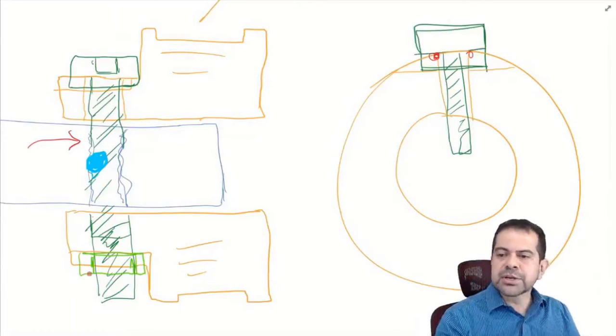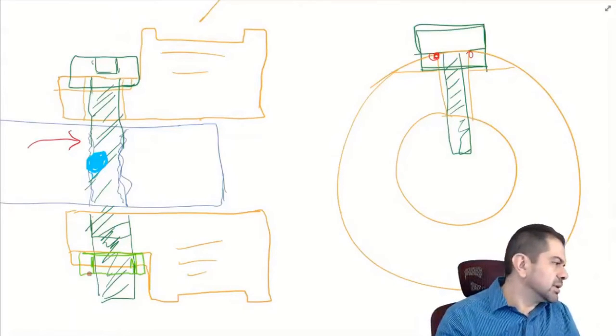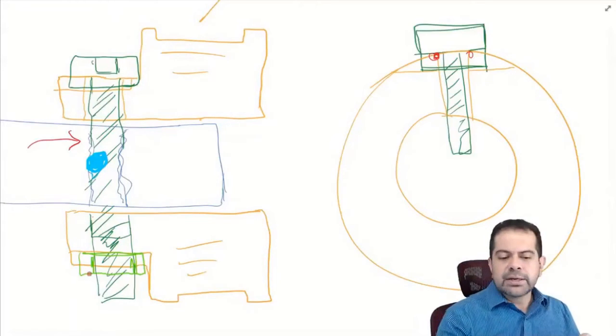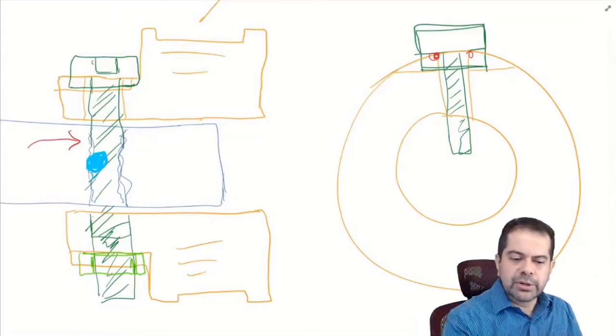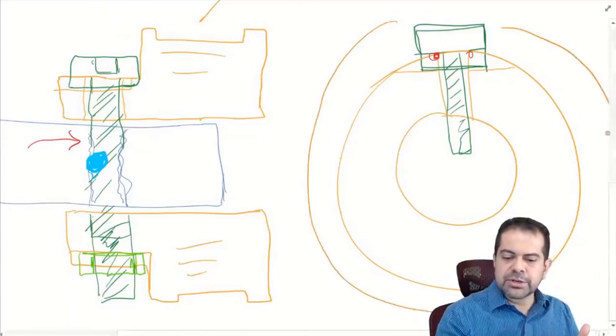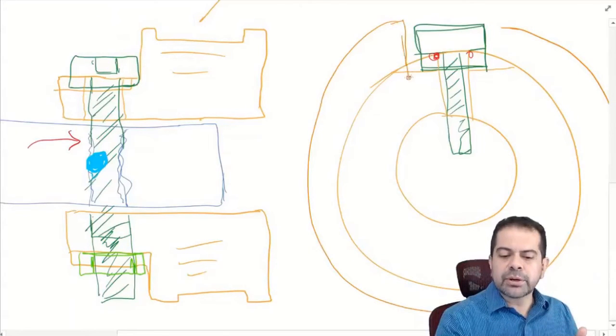Things to consider, and we're about to wrap it up. You suggested a counterbore. Yeah, if you have enough of a surface, depending on the size of the parts, you could add a counterbore. I think what you mean is this. If, let's say, the outside, and I'm going to exaggerate it, is much larger, rather than a flat, you can counterbore for the head of the fastener.